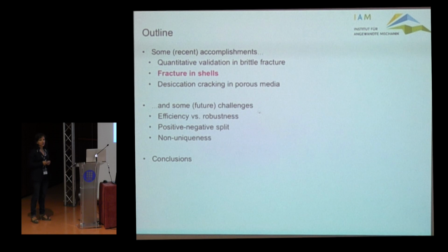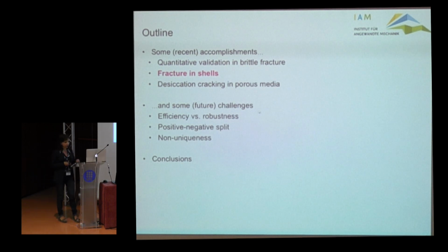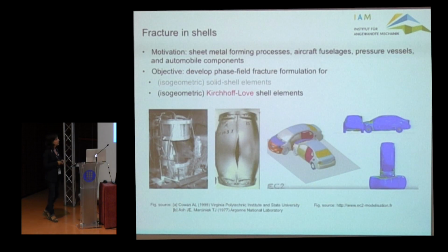As I said, another topic that we wanted to address was fracture in shells. Of course, there are many motivations for dealing with shells. They are used in many fields of engineering. For efficiency purposes, we addressed fracture in solid shells first, but that was not particularly challenging because solid shells are nothing else but solid elements with some cure for locking.